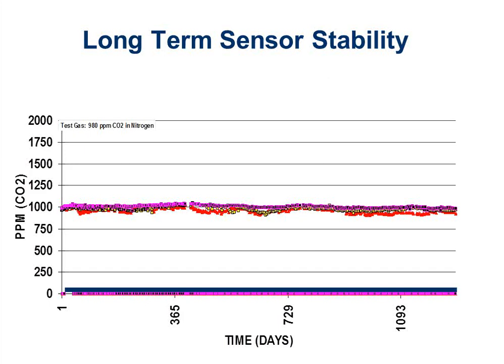It works so well that our sensor manufacturer started taking the calibration buttons off of their hardware. There is no longer a way to calibrate it. It's literally impossible. And the reason they took the button off is because what people would do, they take the cover off the thermostat, they would see a button, and whenever you see a button, your instinct is to do what? You press it. Well, they would press it and basically zero out the reading because they weren't running CO2 or nitrogen through the thing. They'd zero it out, and then the whole thing would be jacked up. So now you can't even calibrate it.